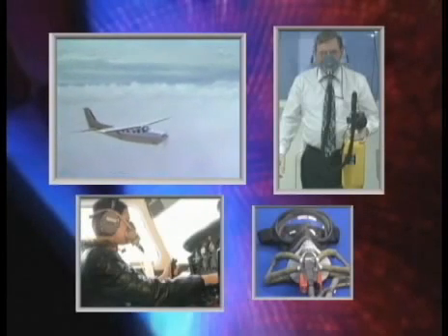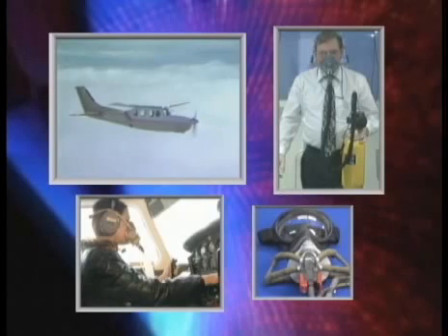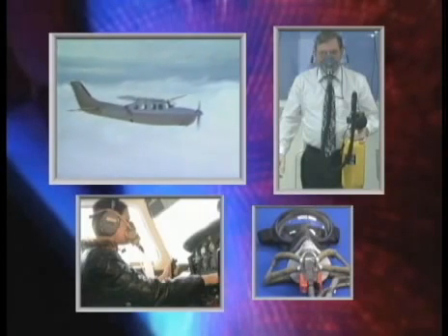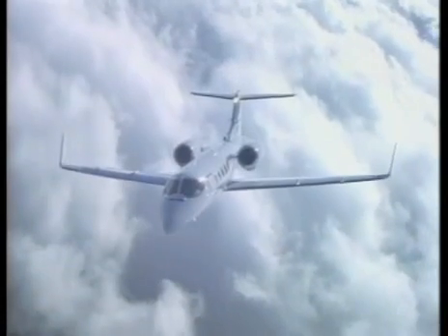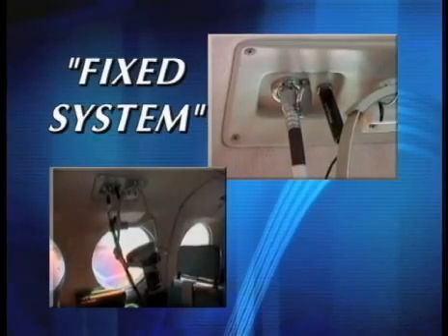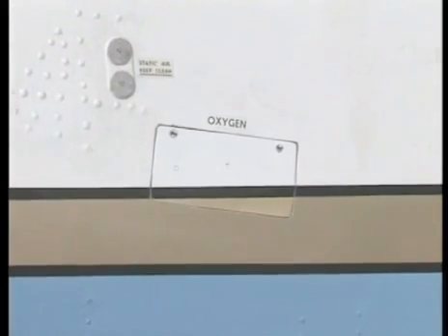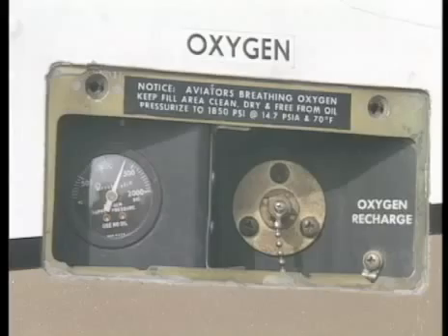The aviation industry has designed and manufactured widely diverse types of oxygen equipment for the general aviation aircraft. Pilots who routinely fly at altitudes above 10,000 feet mean sea level commonly use a fixed oxygen system. Fixed systems are normally serviced through an exterior fuselage valve. The major advantage of a fixed oxygen system is greater oxygen storage capacity.